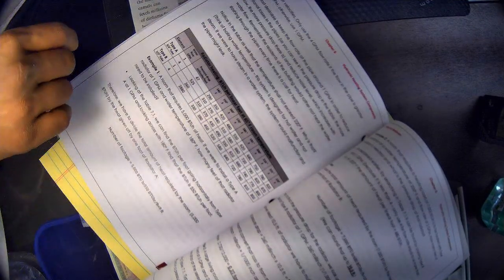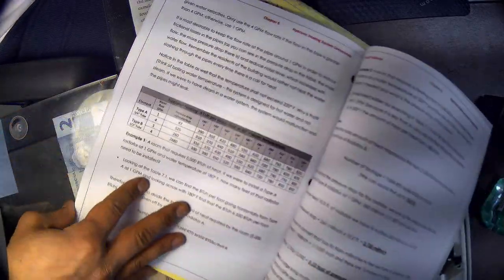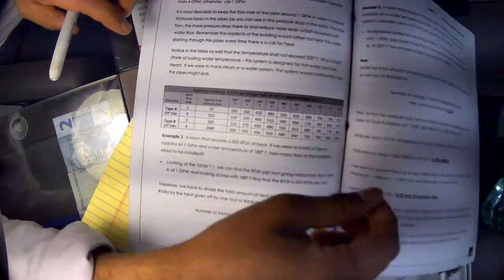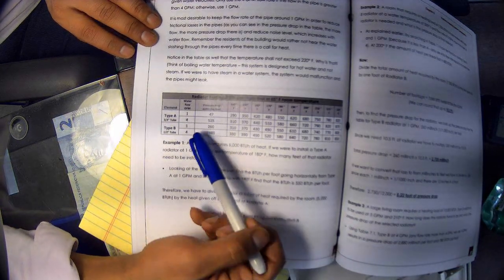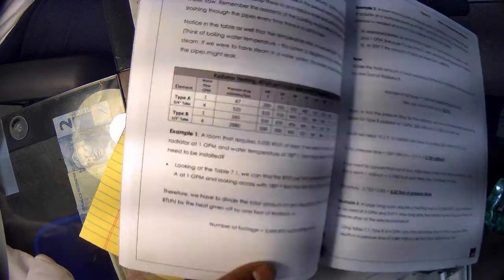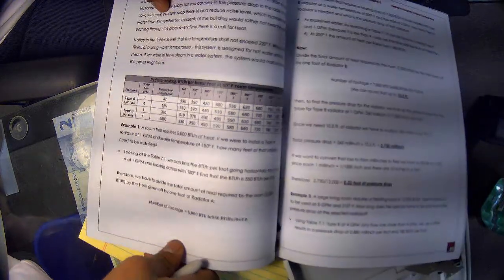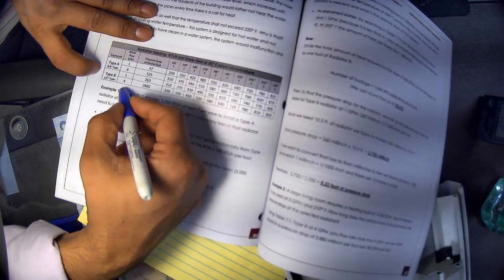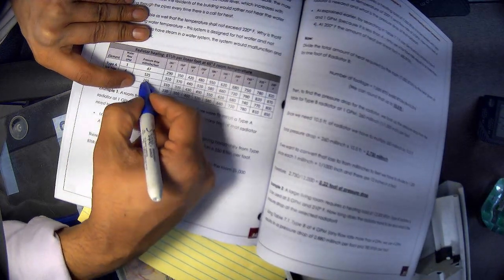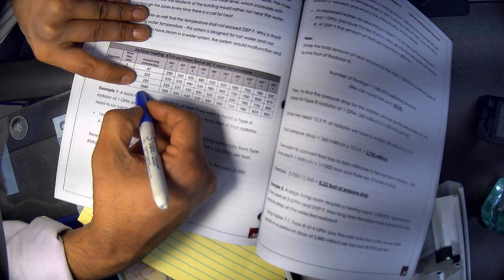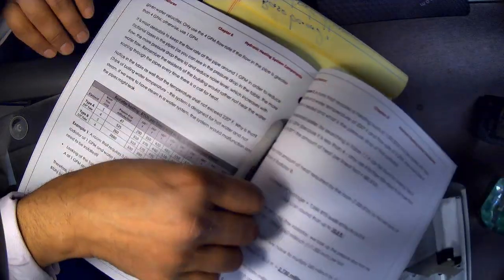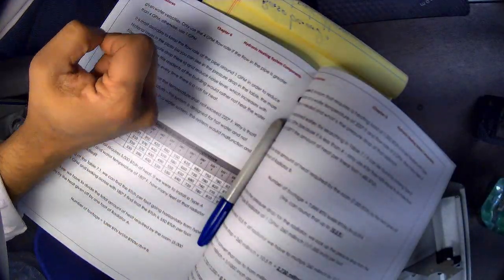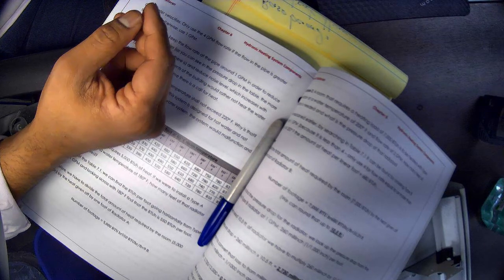So that's how we use the other information in the book. If you look closely here at the book, there's also the pressure drop in milli-inch per foot. So look at it closer in your book, probably it will be clearer. And also it's in the previous presentation. And we went with 5, so it's going to be somewhere around here. So I'll go with the nearest thing, which is 2,880 milli-inch per foot of pressure drop. And the pressure this time is given by foot of water. This information is very needed when you calculate the pressure for the pump.